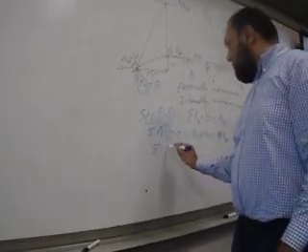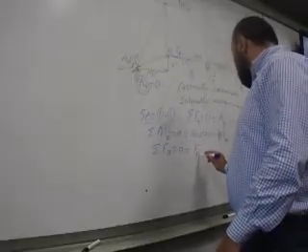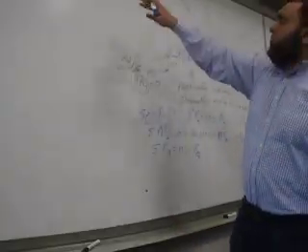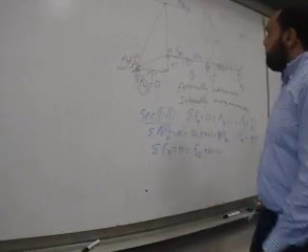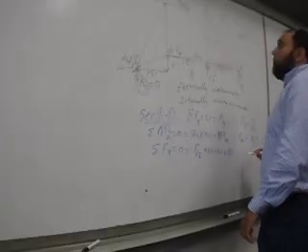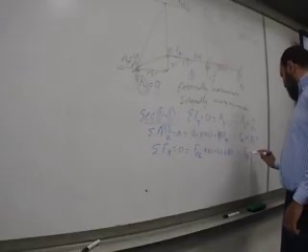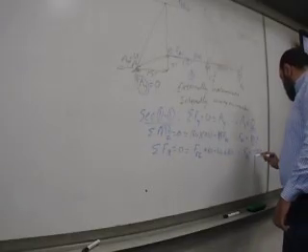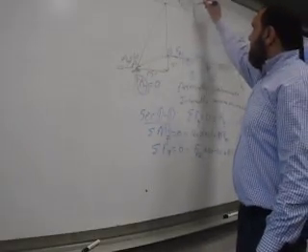After that, sigma Fx equals 0 equals FFE. Look here, we're looking at this part. So it's plus 60 minus 60, plus FBC, which is 80. Therefore, FFE is negative 80 kips. Negative 80. So this part is completely solved.